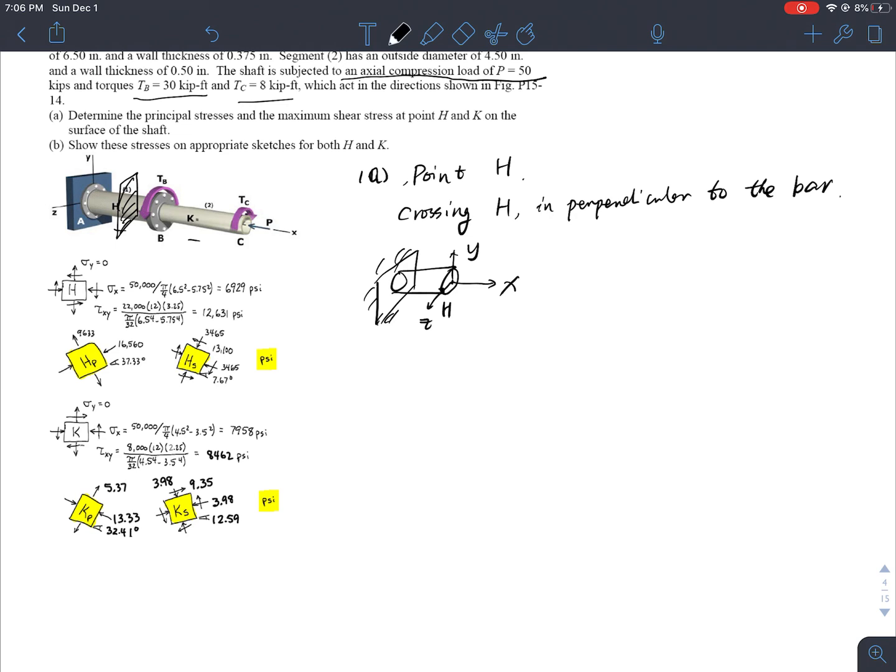Okay, so let's make a little bit of a table here. What type of force do I have? So first of all, I have a compression of P. Okay, compression of P. Okay, and the other thing I have is a torsion. Okay, so this torsion here will equal what? Will equal TB minus TC. TB minus TC to maintain the balance, isn't it? To maintain the balance.